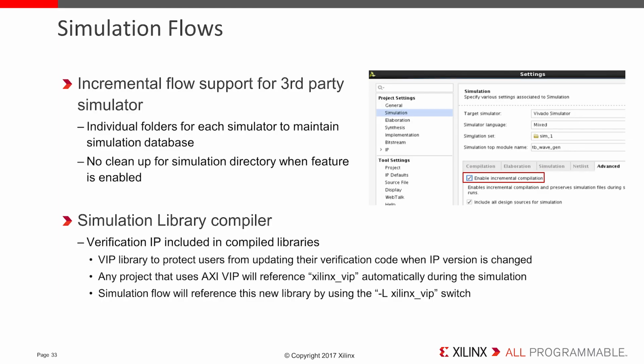For incremental compilation and simulation flows, until now, we were storing the simulation database in one common directory and were cleaning it up on relaunching of the simulation. Due to this, third-party simulators were not able to take advantage of the incremental flow that they have supported for years now. Now there are individual folders for each simulator to maintain the simulation database. Therefore, if incremental compile is selected, then the tool will not clean up the simulation directory.